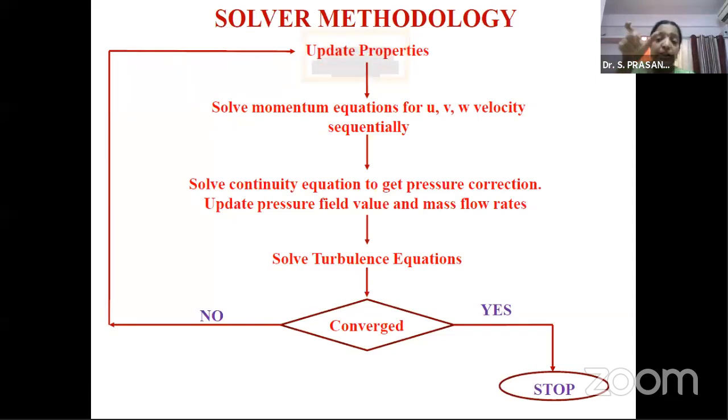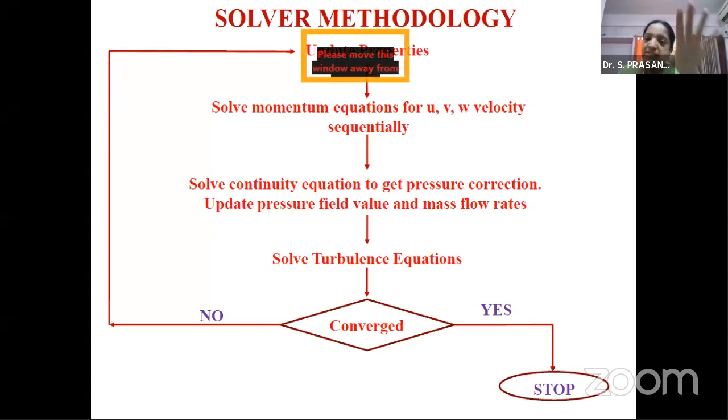This is the SIMPLE solver methodology. Normally everybody adopts this because it requires less space, it is faster, and so on. So we have also applied the SIMPLE methodology. What is the solver algorithm that runs behind the SIMPLE solver methodology? It is the pressure correction method. Now, what is this pressure correction method?